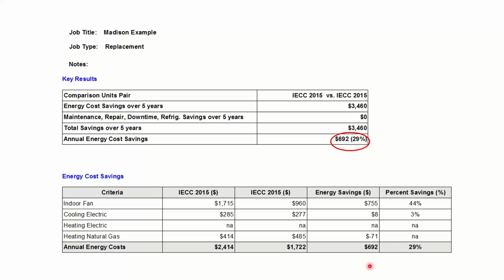At first when we started doing these calcs, we were like, why is this happening? Motors, if you didn't know, have a little bit of waste heat associated with them, and that waste heat goes into the airstream. So when I slow the motor down, it has less waste heat, which means I need a little bit more real heat from the gas side to make that up. But I'll happily buy $71 of gas to save $750 of electricity. That's an easy no-brainer trade for me.